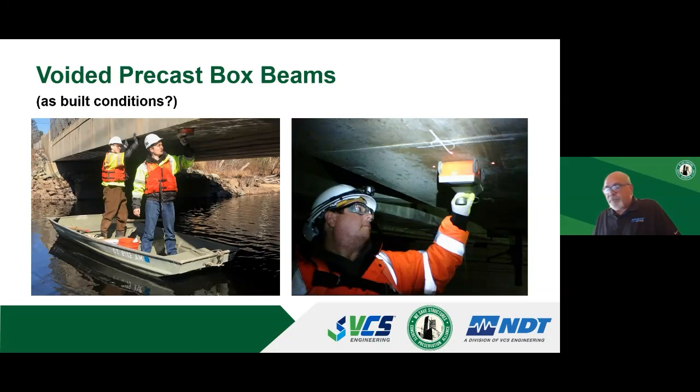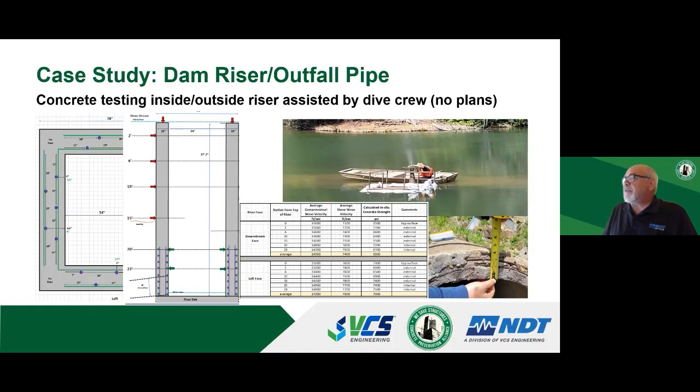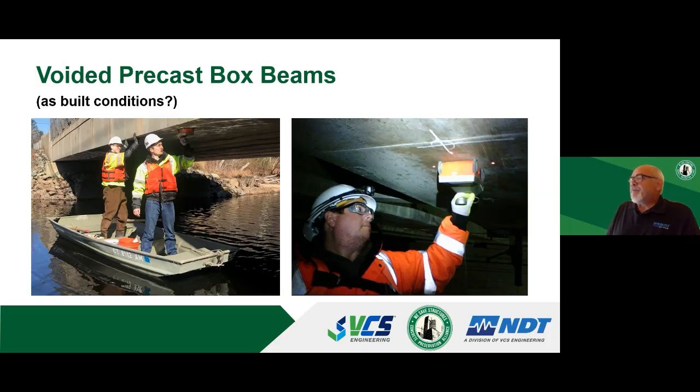Another example is a riser on a dam where there were no plans available, so we did some investigation and quantified the condition of the concrete and the presence of rebar. Some of it was underwater. We put our equipment in the hands of divers and came away with a good picture of what was in place there.